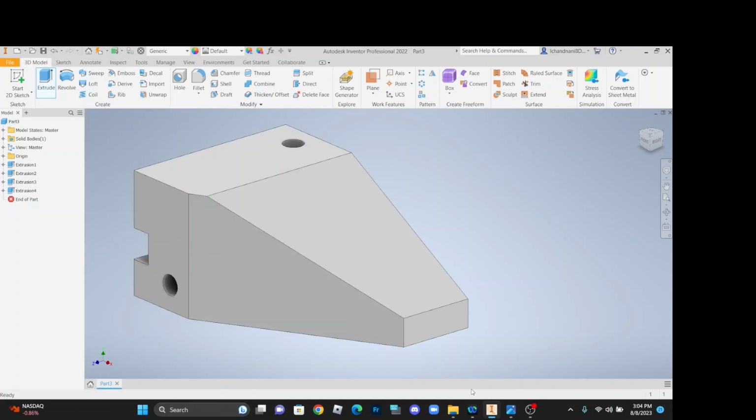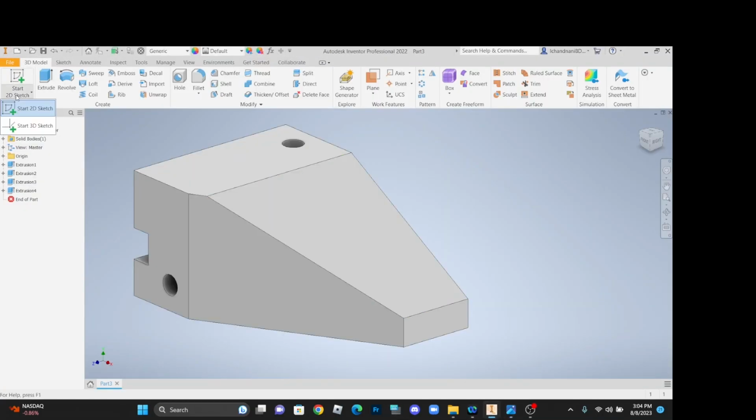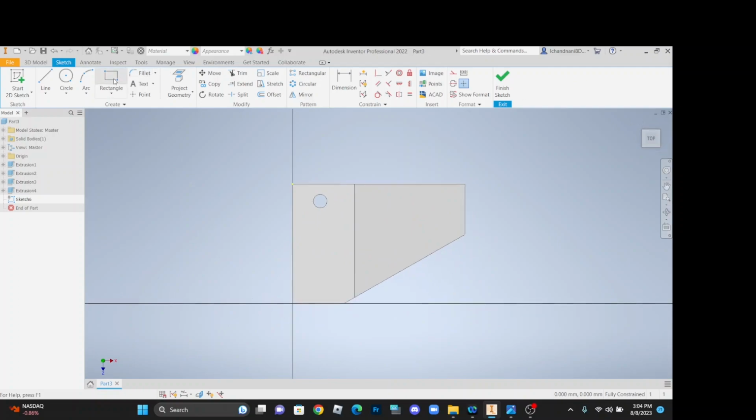You click OK. Now we have this notch here that's 75 millimeters by 25 millimeters deep, which is this right here, 75 and 25 deep. So we will start off with another sketch on this plane. Let's just rotate, and let's pick a 2-point rectangle. So you pick this, and let's just start it here and go across.